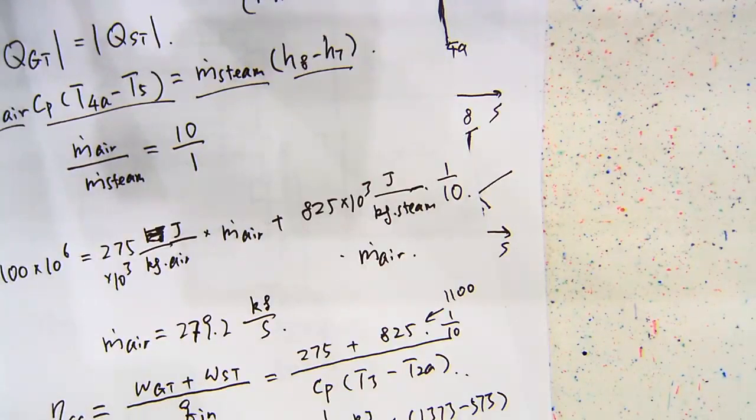So I've got a problem about the gas turbine. A normal gas turbine has a T-S diagram like this one. This is the inlet temperature of the turbine, and this is the outlet temperature of the turbine. So we get this equation. But if it's a turbojet, where I add a nozzle behind the turbine, this temperature 5 is the temperature at the nozzle. So this equation becomes T2 over T1 equals T3 over T5.